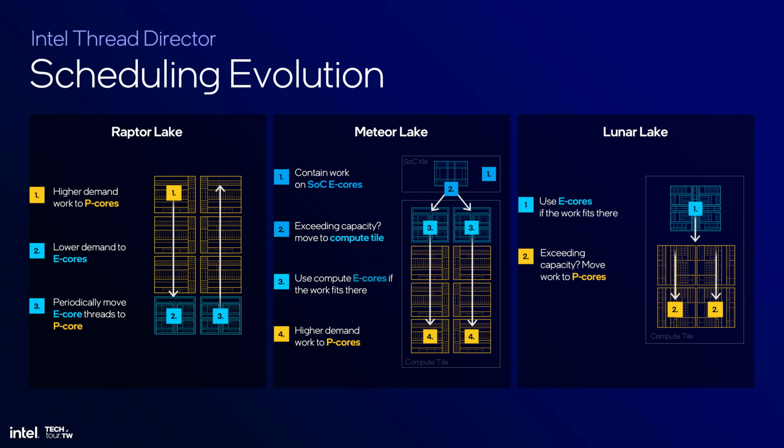Now, as we evolved into the low power island, Meteor Lake, Arrow Lake, Lunar Lake, Meteor Lake and Arrow Lake were really our start to that. We started to give options to our customers, where Thread Director would provide feedback to the operating system that these are the most efficient cores to start from. And then there is an option to use hetero scheduling that we discussed earlier, where an OEM can choose through a PPM package and say that I want hetero scheduling for when I'm unplugged, I want to maximize efficiency, right? And start from there.